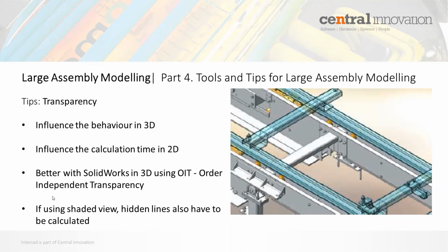Around about 2014, SolidWorks optimized for using order independent transparency. So if you've got a graphics card which is newer than about 2014, it should also be optimized to use OIT. It's a hardware function on the graphics card that SolidWorks will support if it's there.